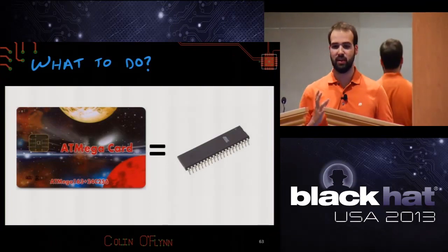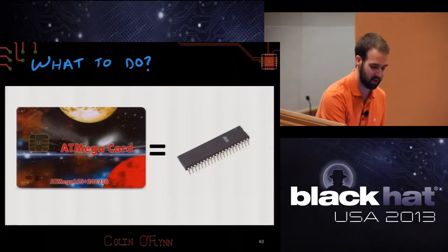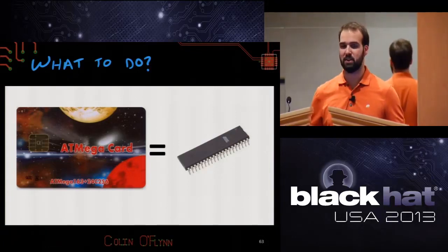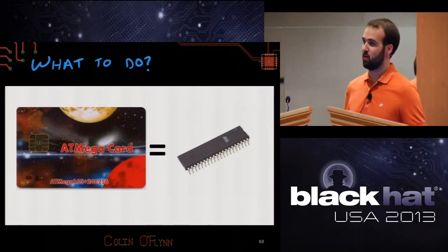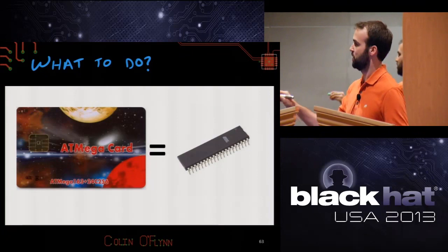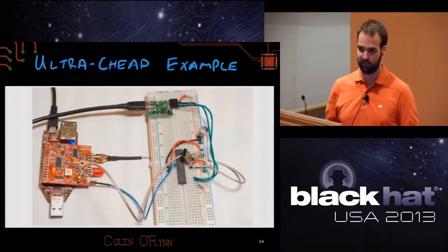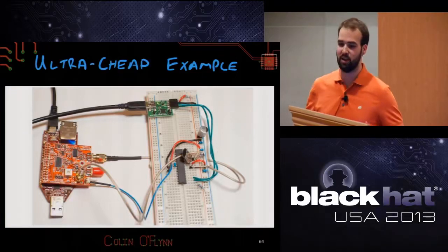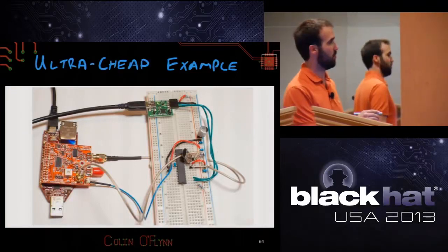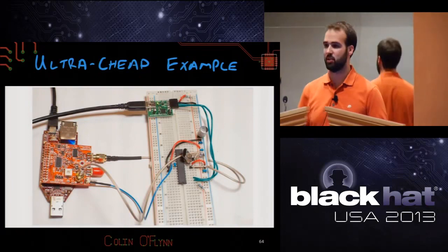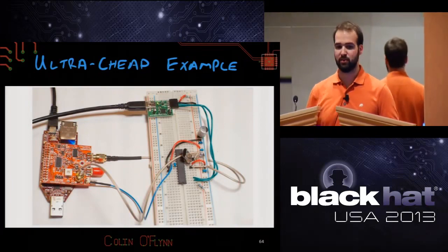In fact, you're doing a disservice by using these AT mega cards because they use an old microcontroller that has much larger power signatures because it's a larger geometry. You can buy a recent microcontroller and just program it yourself and you save yourself that hassle. So this might look something like this if you wanted to get into it. You have a microcontroller on a breadboard and you have some support circuitry around it, basically the USB to serial converter and some power supply filtering.